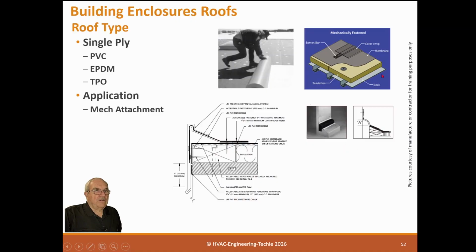Now the membrane layer. So this here is like a steel deck. And then this would be the built-up insulation, which is rigid. And that is normally screwed to the deck. It might actually be glued to the deck, but normally it's screwed. What you need to pay attention to here is that this is not just flat. They build up what we call crickets. They build this up to be able to channel the water toward the drains. So they build this up thicker and thinner to produce that slope. So that's one thing you need to check.